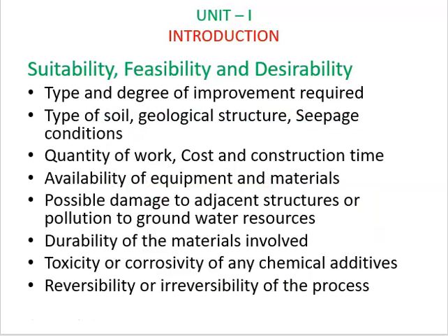Next topic is suitability, feasibility and desirability. There are various factors which influence the selection of ground improvement technique for a particular site. First one is type and degree of improvement required. Before we select the ground improvement technique, first we should understand the problem at the site, whether the problem is with low bearing capacity or excessive settlement or slope stability or permeability or liquefaction or erosion, etc.